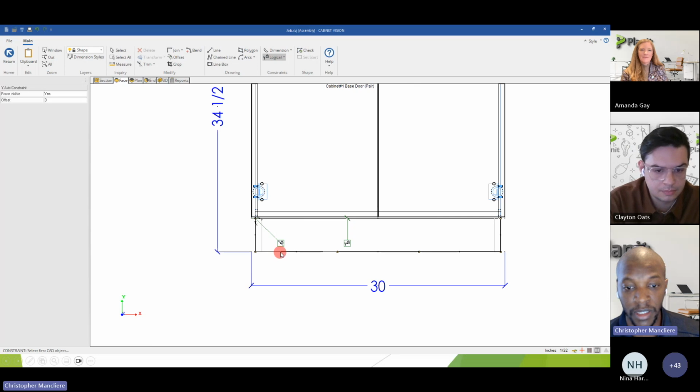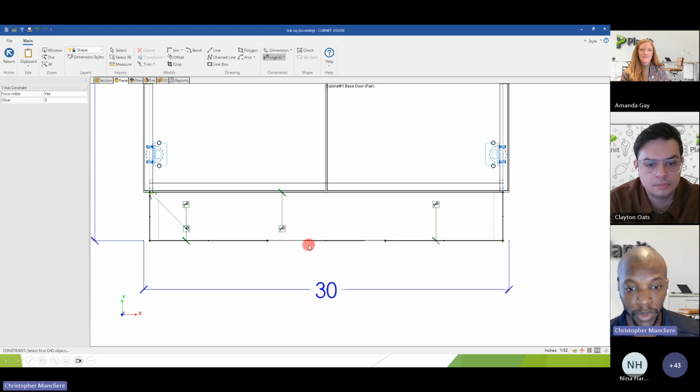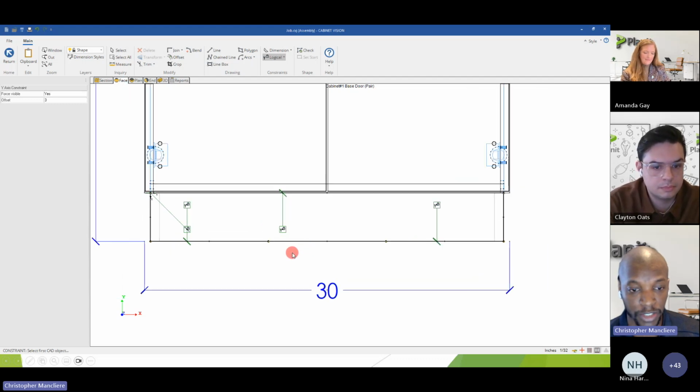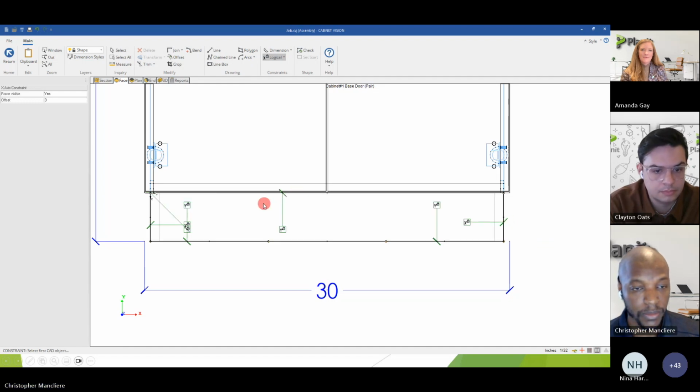This is Y, and this is Y as well. I don't need to add an X or Y axis constraint on the middle segment just because this is going to be an arc, so it's not going to follow any specific direction. So I'll just do those 2 end segments, and also I'll do an X axis constraint on the left and right segment as well. So this is now with fix and also X and Y axis constraint.